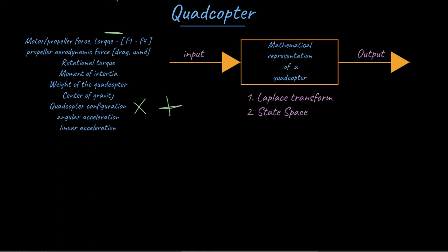So now I don't have to just subject it to one particular speed, but if I keep changing the speed, how does the quadcopter behave? Then you're not just doing a single instance and mapping input to output, but you're also mapping frequency, the change in input, to how the quadcopter behaves. And that's what we're trying to do. We're trying to understand the system.